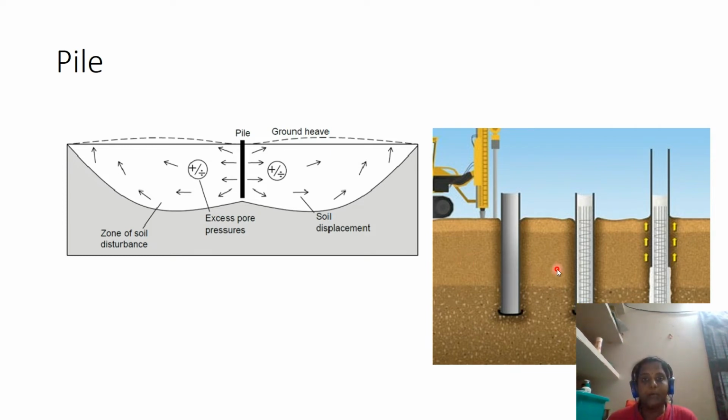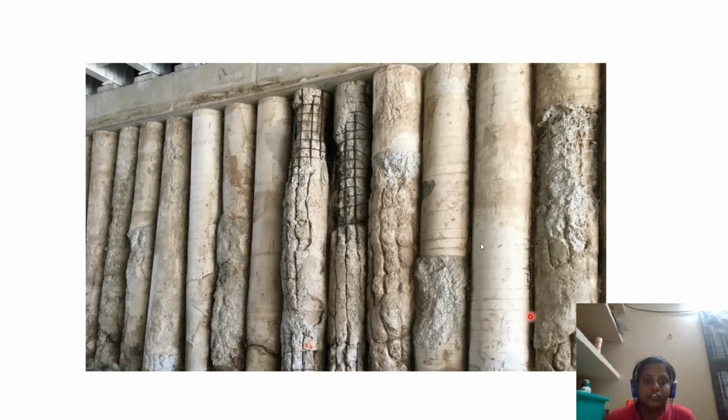So it is very important to conduct pile testing, dynamic pile testing, which is a non-destructive testing. I will also show the other possibilities, but here we can see that sometimes the concrete is not properly formed around the reinforcement cage.